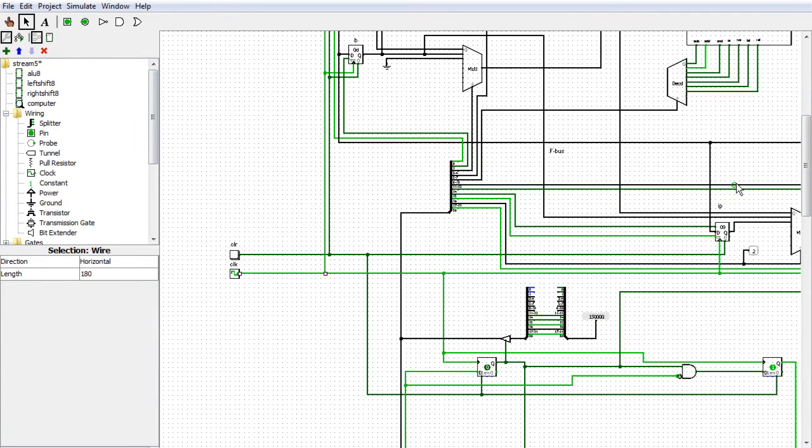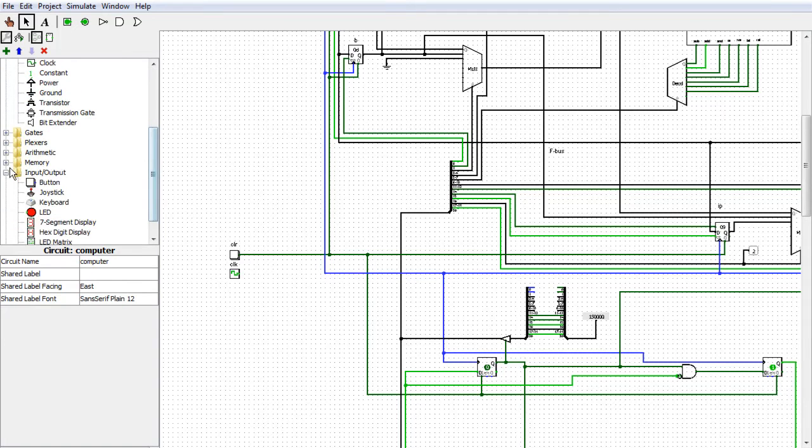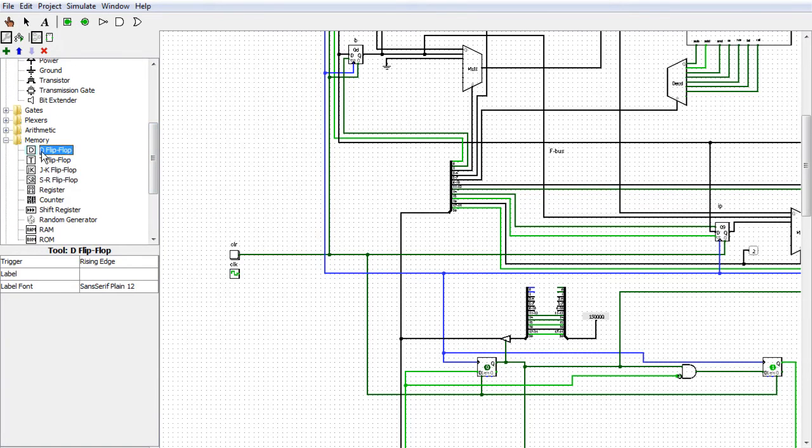So this can be solved rather easily with a little bit of logic. What we're going to do is add in here a little piece of memory, a little flip-flop here. And this flip-flop, should it be a set reset maybe? Or a D flip-flop? I'm thinking set reset flip-flop here. All right. And what we're gonna, no. It's gonna be a D flip-flop.